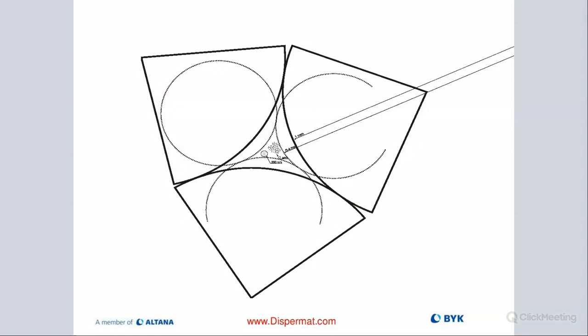And it's happening actually as the beads collide. Right in that corner is where that shearing takes place, and a lot of that force is created that's causing that shearing of our aggregate, and therefore breaking up these van der Waals forces and reducing our particle size down to primary particle size.